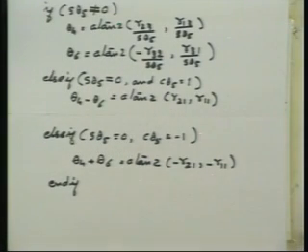There is a possibility, that is if R33 is less than 1 in magnitude, there are two solutions. If it is equal to 1 in magnitude, then there are an infinity of solutions. We can get only theta 4 minus theta 6.